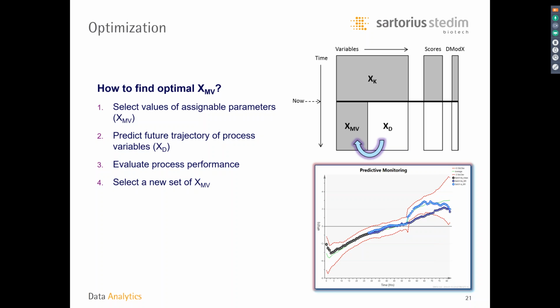You can even put objectives like that into your controller objective. That goes into an overall penalty function. Maybe I'm getting a little technical here, but basically we have multiple objectives we're trying to accomplish, and the optimizer finds the best way to accomplish all of these simultaneously. It evaluates how close it got to all of its objectives, then tries a new set of manipulated variables. It iterates and sees whether that new set made the objective better or worse, using a direction of steepest descent to find the global optima.